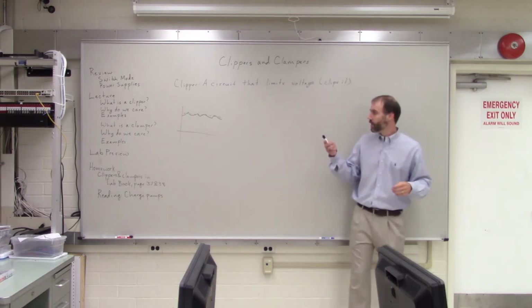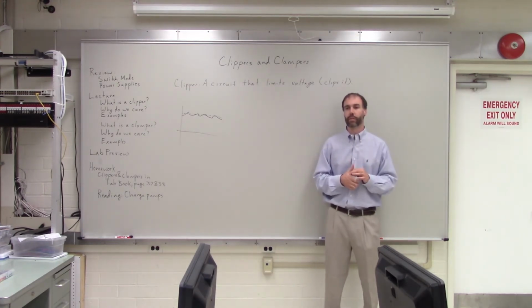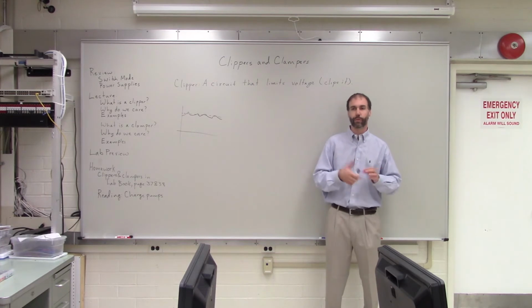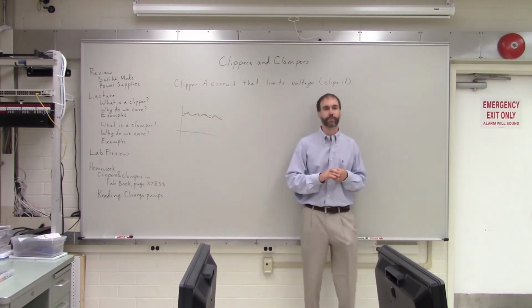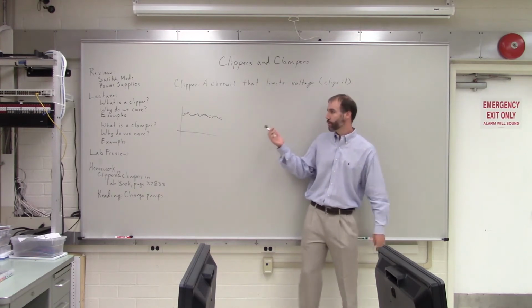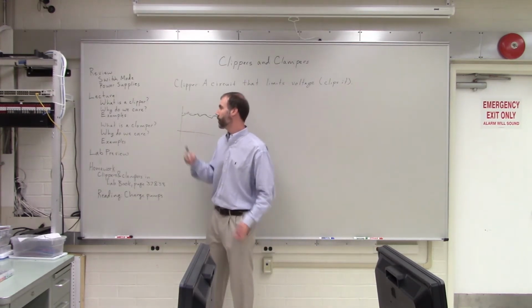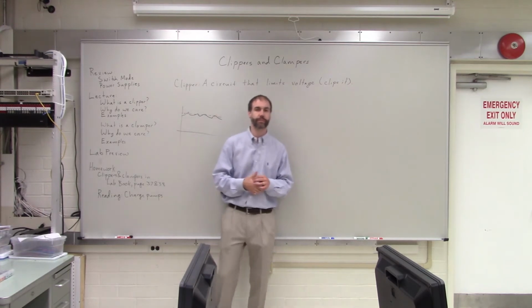So it clips voltage spikes? Yeah, exactly. It gets rid of voltage spikes. It gets rid of any voltage above whatever level you set. So safety or protection circuits are common use for clipper circuits.